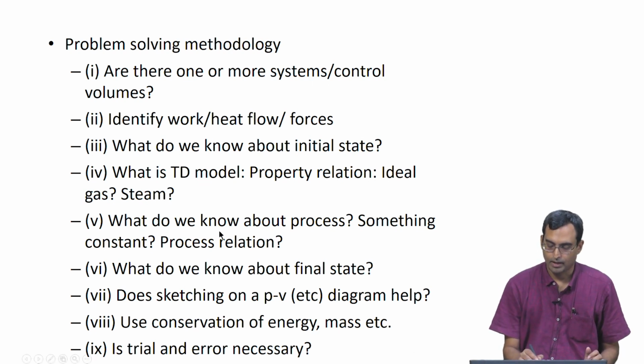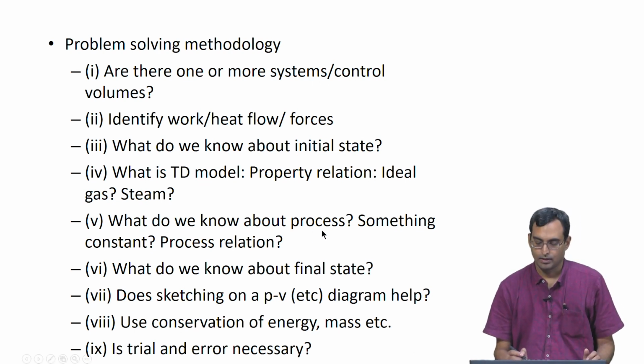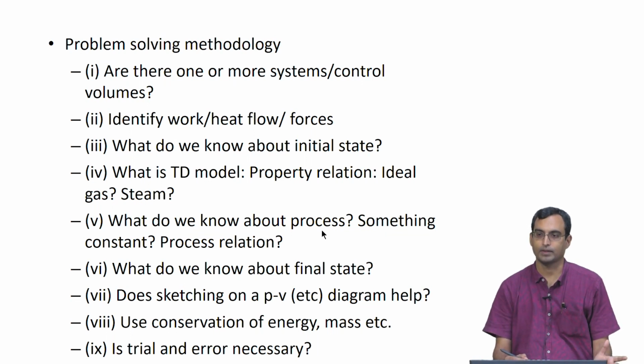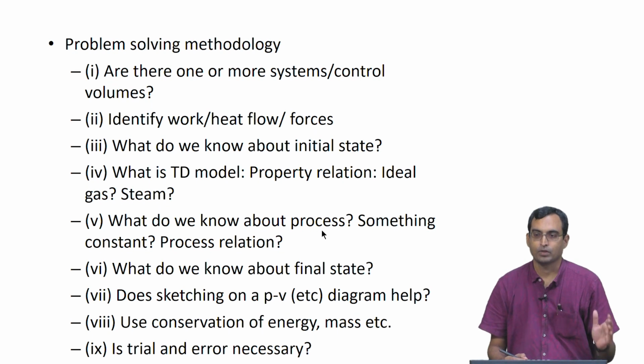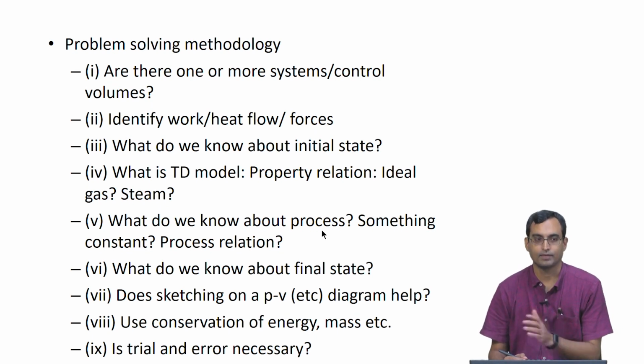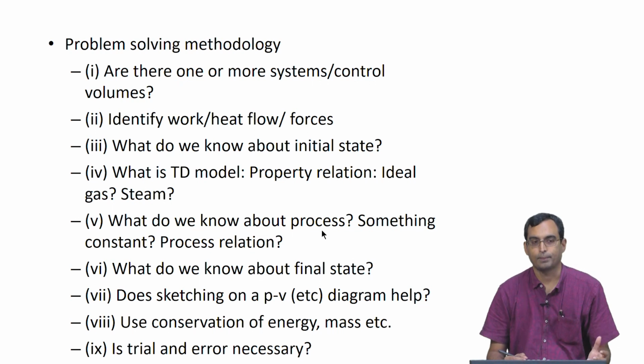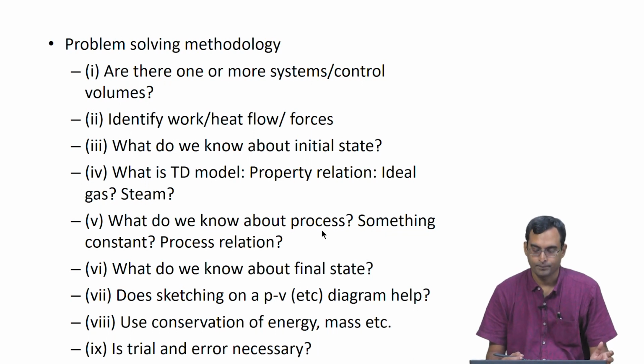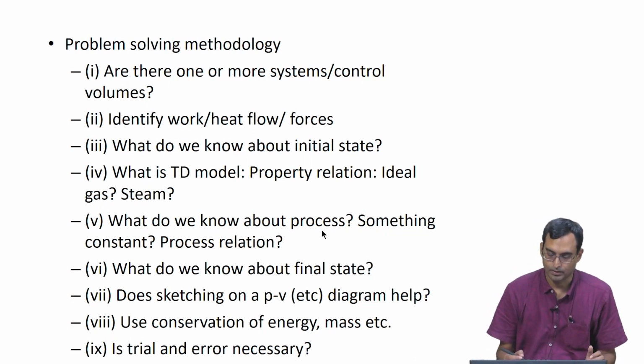Then we will see what we know about the process. Is there something constant? For example, is pressure constant and is it an isobaric process? In which case, knowing the initial state and knowing pressure is constant, we know something about the final state. Is temperature constant? Is volume constant? Is anything at all constant? Or in case things are varying, do we know how they vary? That is something which we will try to find out.